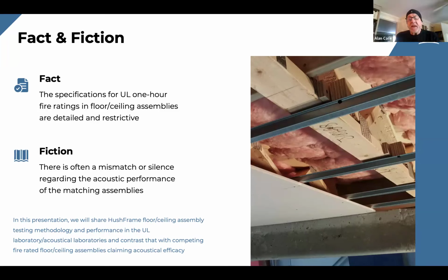It's just that what we'll show you is that the representation in the marketing materials from the metal channel product companies shows a specific STC or IIC rating for installation, but those ratings that they publish don't necessarily comport with the installation requirements of a UL assembly that meets fire code. And so there's a real disconnect there. What we tend to do is show our product in field testing application once it's been installed and then tested acoustically in an approved UL assembly to show the difference in performance.